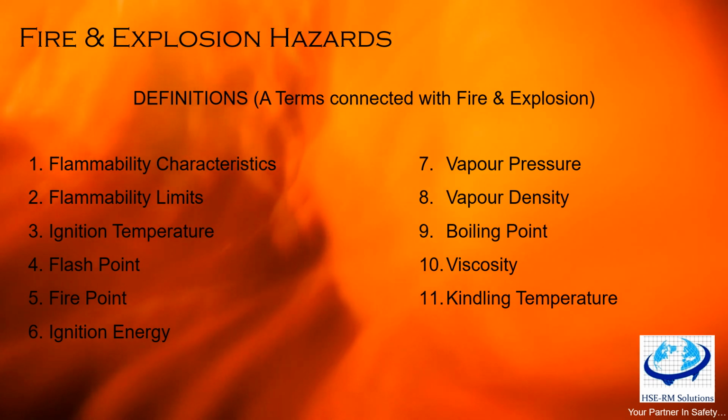Now the second definition that you must know is flammability limits. A flammable gas burns in air within a limited range of composition, correct? The lower flammability limit is such that below this limit the mixture is too lean to burn, and it is also called the lower explosive limit, that is LEL.